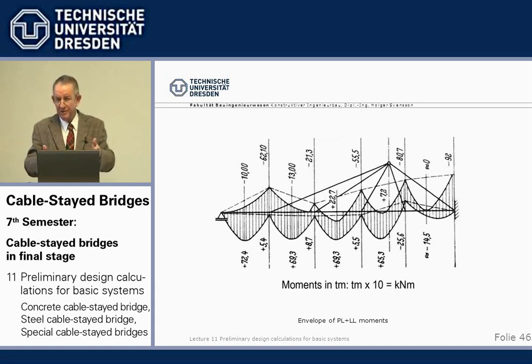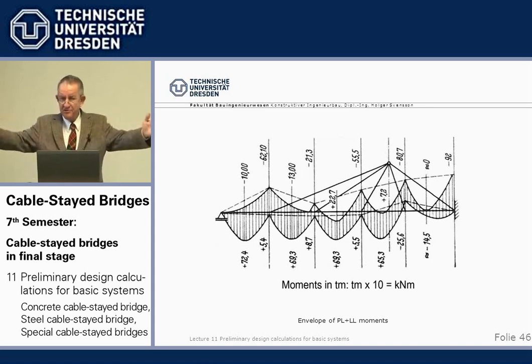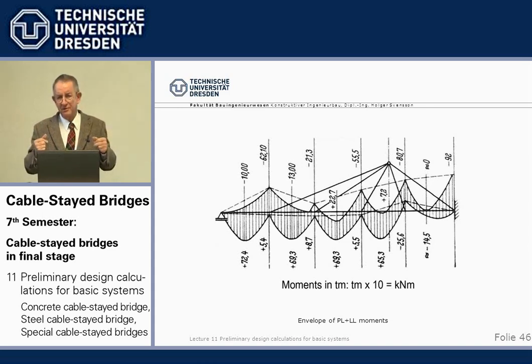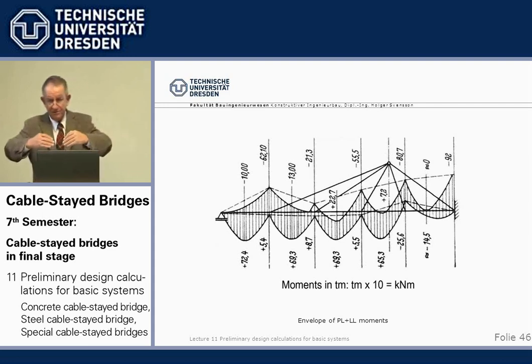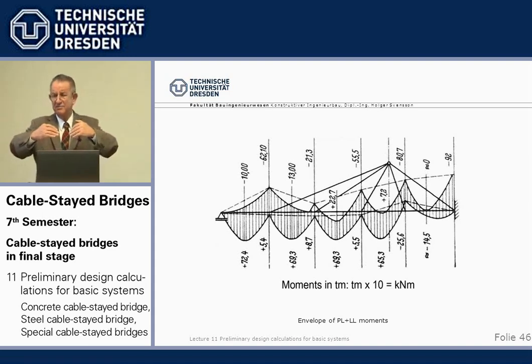It's only the width of the box without the usual cantilevers the top flange has. So, for a usual road cable-stayed steel bridge, we introduce rather high negative moments under permanent loads from the different moment capacity.